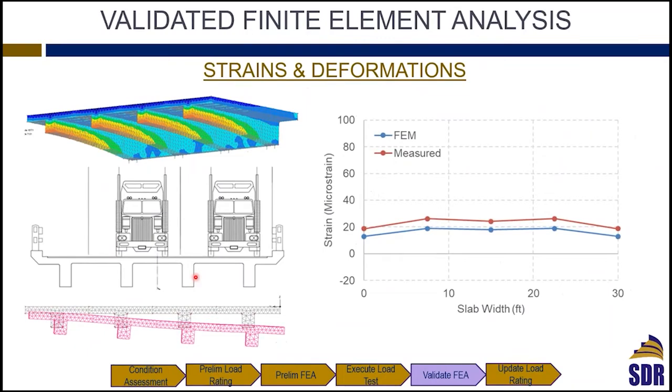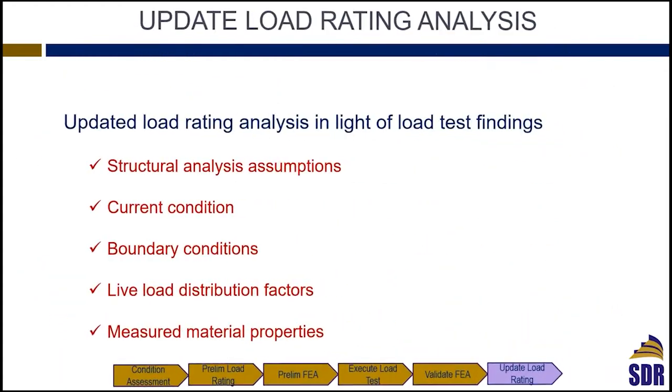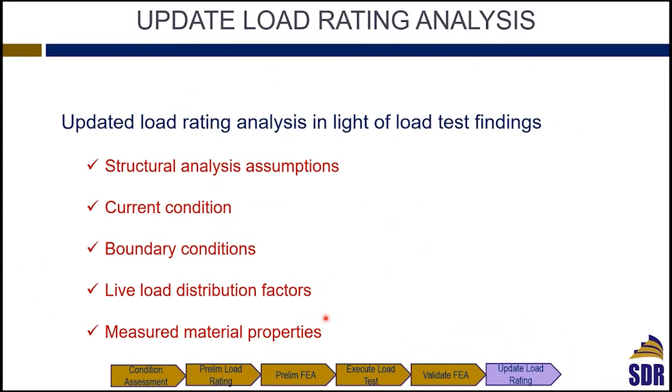Now, after we take our field measurements, we come back and start comparing the field measurements to the finite element model, and then we start validating our finite element model by comparing the field measurements to the finite element strains. And we do that in terms of comparing stresses and strains, and also comparing the deformed shape of the bridge to what we're expecting.